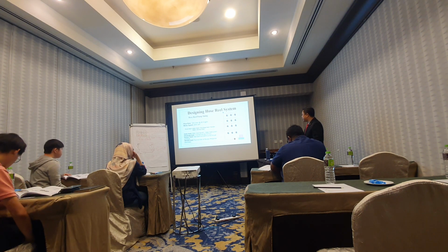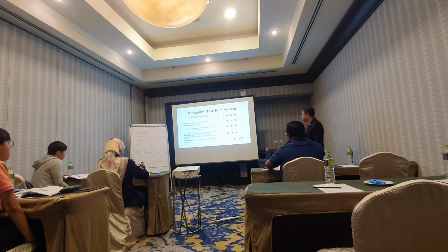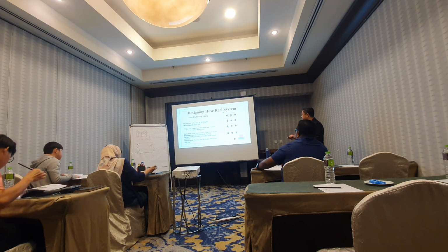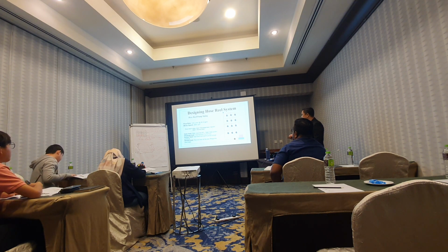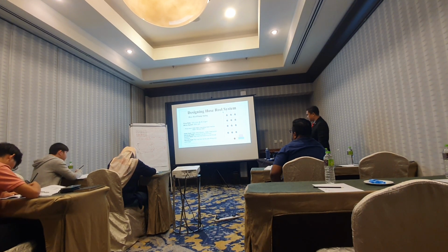To calculate the pump size, you will have the static head, which is the height distance, and the discharge head. We have a discharge head of 2 bar, which is already catered for, as spelled out in the Malaysian standard. And then the suction head plus the delivery head. The delivery head is the pipe loss.